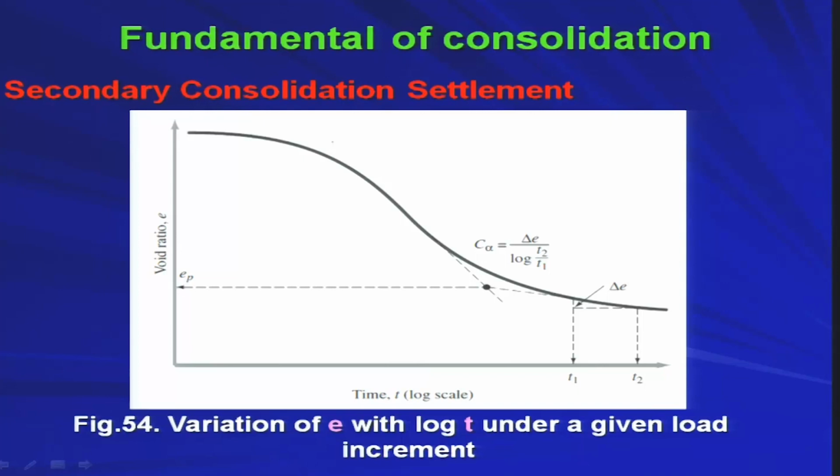So, basically you have the curve like that. Okay. So, initial flatter part, then the steeper part, right. In this part you will be having some steeper slope, and then basically after this point, you will be getting some flatter, I mean curvilinear part. Now, if you extend this straight line part and this straight line part, you will be getting some point here. So, from this point onward you will be getting some secondary consolidation. Okay. So, now let us find out the secondary consolidation.